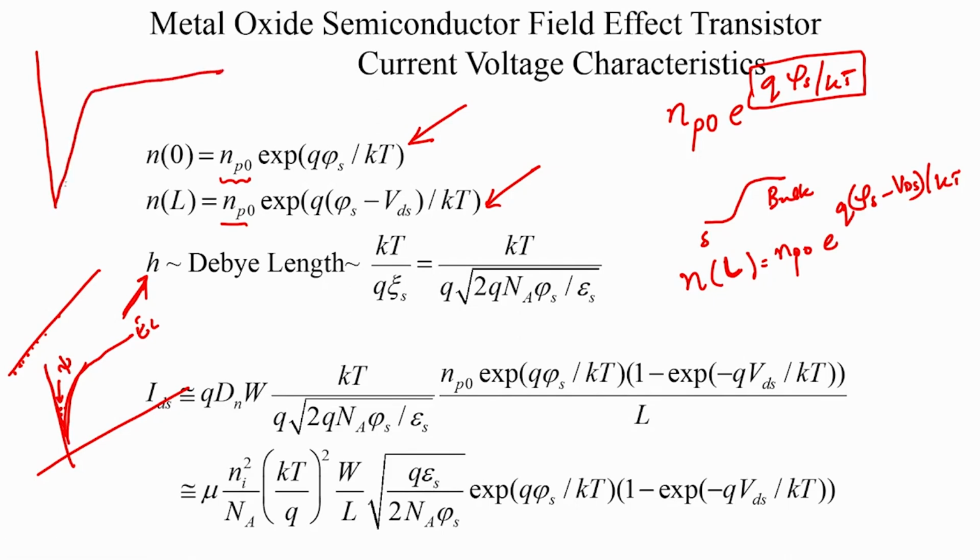If I approximate everything like this, and draw my conduction band diagram like this, and say that this is the insulator, you have electrons that have a certain wave function sitting inside this box. And what is the potential profile? On the left side you could say is a finite potential barrier because of the insulator, and on the right side is a triangular potential barrier, and the electrons also experience significant electrostatic interaction between each other, and that also gets involved in the potential term.